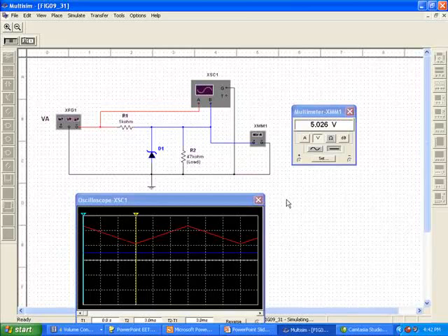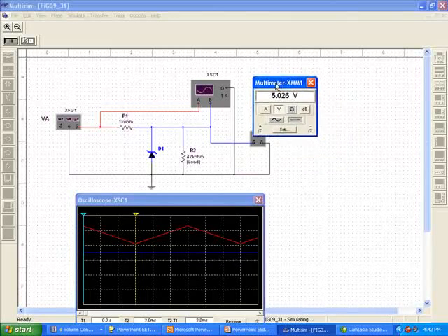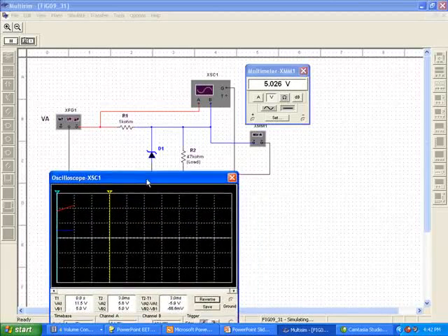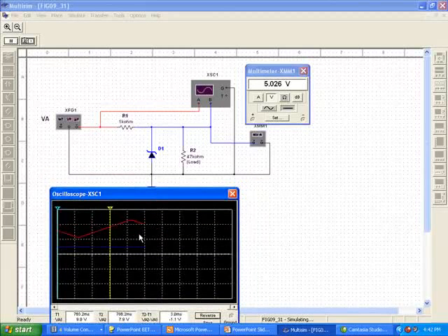Earlier we had talked about computer circuits that needed a stable DC voltage, and Zener regulators are commonly used in that application. And remember that the computer needed to have 5 volts, and so when the AC comes in, the AC is going to have ripple in it, and it can vary from the wall. The Zener here is capable of stabilizing that value, and you can see quite clearly that we have an input that is changing quite radically, and yet the Zener is able to keep that voltage very stable.